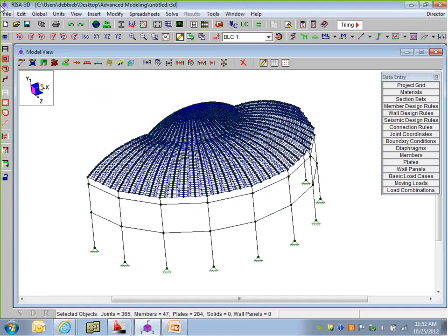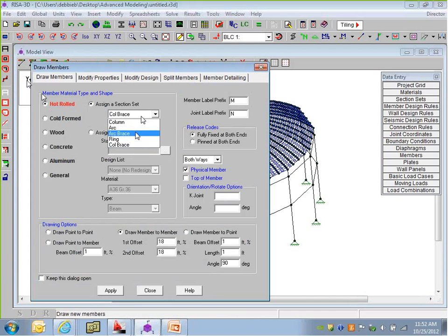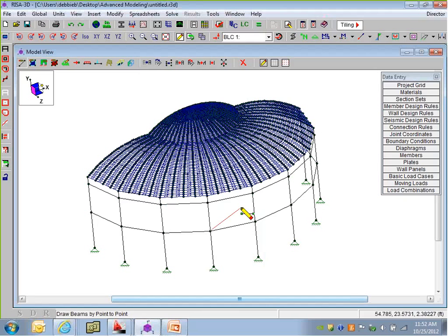You want to try to quickly get in and out of your model. So we've got here, I'm going to just do, again, some column bracing, and I can maybe say pinned. Again, I didn't really pay attention too much to the end releases, but you'd want to do that, point to point, and I can draw in some of this bracing. So I'm going to say the bracing goes here like a big triangular bracing in that.